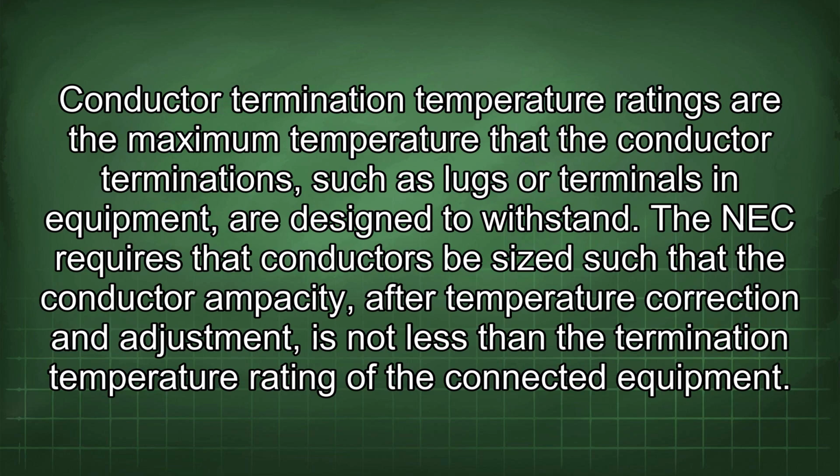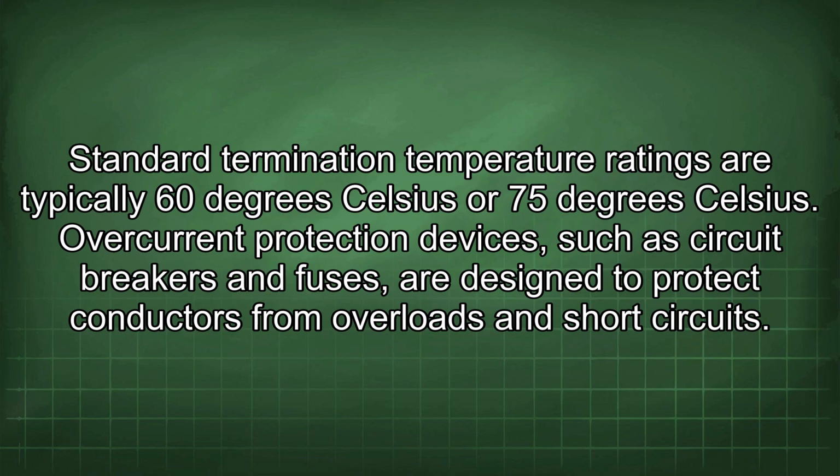Conductor termination temperature ratings are the maximum temperature that the conductor terminations, such as lugs or terminals in equipment, are designed to withstand. The NEC requires that conductors be sized such that the conductor ampacity after temperature correction and adjustment is not less than the termination temperature rating of the connected equipment. Standard termination temperature ratings are typically 60 degrees Celsius or 75 degrees Celsius.